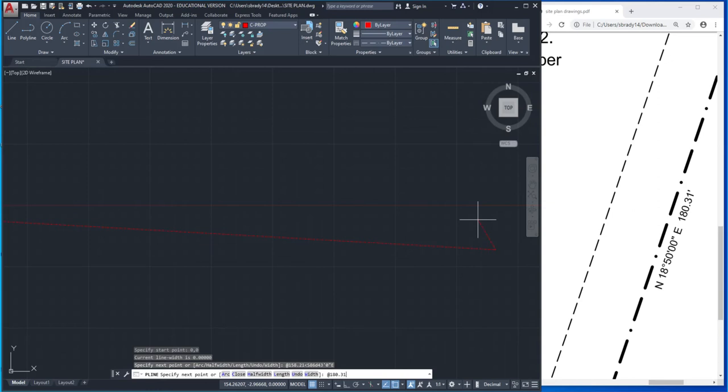I'm going to type at 180.31. Now here's a little trick, okay? Here's what messes most beginning AutoCAD students up when we're entering surveyor units. It's a little tricky too. You see this little foot mark right there, right? We are currently drawing in decimal units. We're in the decimal format. And a lot of students look at this and say, but there's a foot mark right there. And if I enter the foot mark and I'm drawing in decimal degrees, AutoCAD won't recognize it.